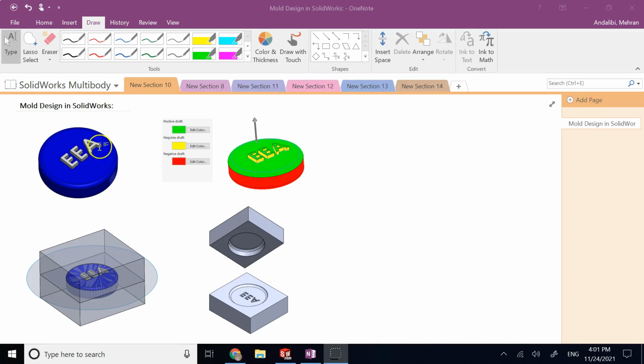So let's say you have this part that you want to manufacture using molds, whether it's casting using molds or injection molding or any other method that needs a mold, because you are doing large scale manufacturing and you want homogeneous parts in terms of properties. You want isotropic parts because with 3D printing you cannot achieve that. You want a smoother part, faster production, cheaper, of course a bigger upfront cost.